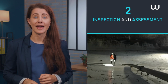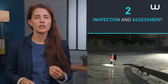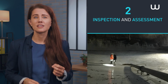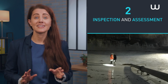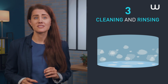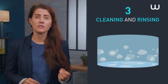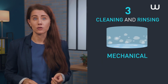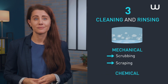An inspection and an assessment are then carried out. The purpose of this stage is to check the condition of facility structures, the presence of deposits, the condition of immersed equipment, and watertight coating. The next stage is cleaning and rinsing. This stage permits the vast majority of contaminants and deposits present on the walls or at the bottom of the tanks to be eliminated. Cleaning can be mechanical, via scrubbing or scraping, or it can be chemical.